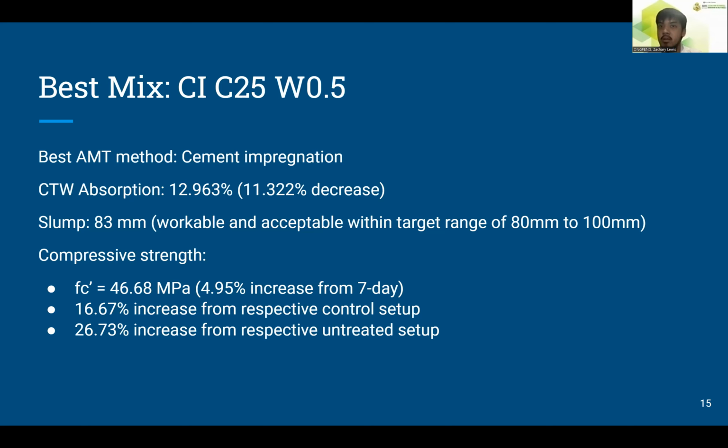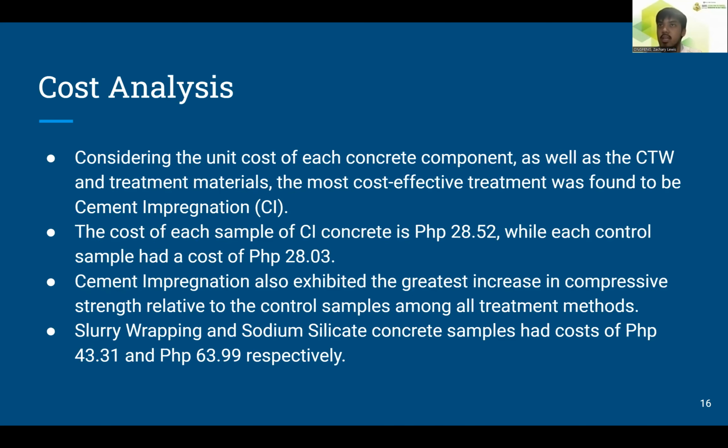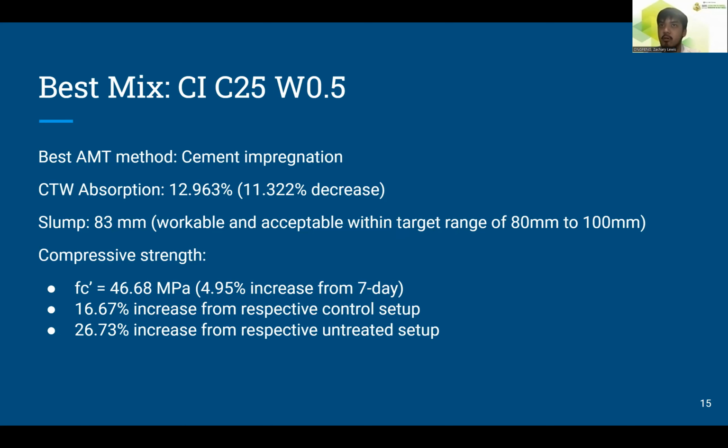So its compressive strength is 46.68 MPa, and it has a 16.67% increase from the respective control and a 26.72% increase from the untreated setup. It is also important to note that the compressive strength value increased by 4.95% from the 7-day sample.